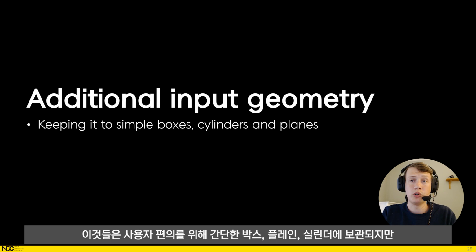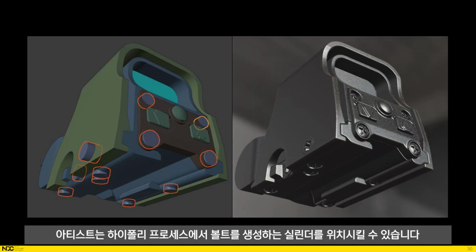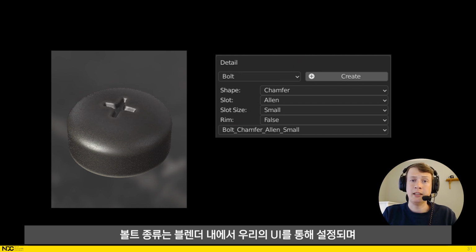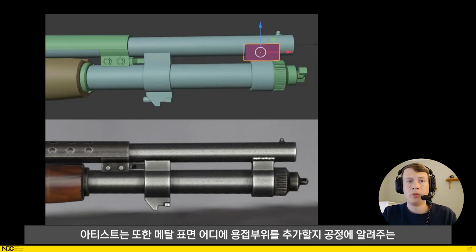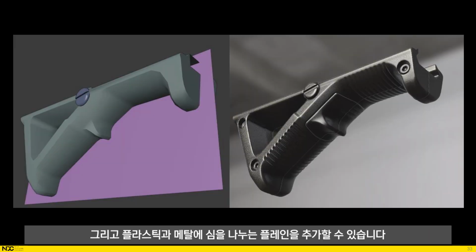They're kept to simple boxes, planes, and cylinders for the sake of user-friendliness, but they tell the process to do some pretty cool things. The artist can place cylinders that will generate bolts in the high poly process. The bolt types are set through our UI in Blender, and all of the bolts are created procedurally in Houdini. The artist can also add boxes that tell the process where to add welds for metal surfaces, and planes that add cast seams for plastics and metals.